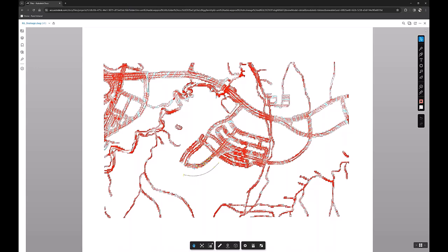If I take a look at that, you'll notice that in the viewer, it opens up to what would be the equivalent of like the model space inside of a Civil 3D drawing. And this is currently just scaling it to the extent of the file. So when I'm looking at this here, it's a huge area of land. And in that case, when we're looking at the standard tools in the web viewer, all of your markup and commenting tools are going to be available here on the right side tool panel. And for this case, the clouding, the text, the boxes, all of those tools are automatically going to scale themselves for the size of the sheet.